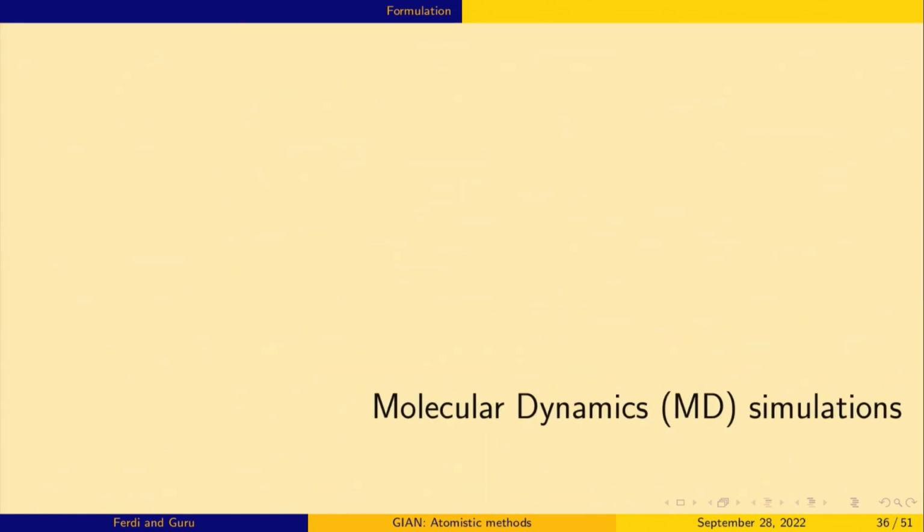So, now we come to molecular dynamics simulations. Now that is the formulation, we know how to adjust the other parameters, so that the Gibbs phase rule is obeyed, we are on that surface, and then you want to evaluate the interface stress associated with the solid melt interface. Because Frolov and Mishin did it for lots of FCC systems, we decided to do it for a BCC system. So, we took BCC iron in contact with its melt and we decided to evaluate what is the interface stress.